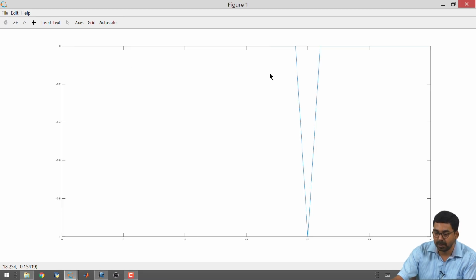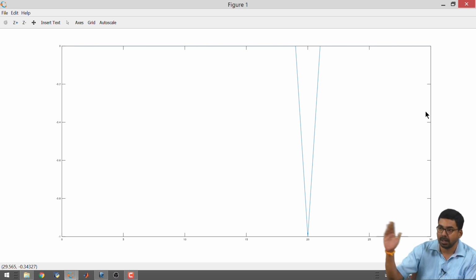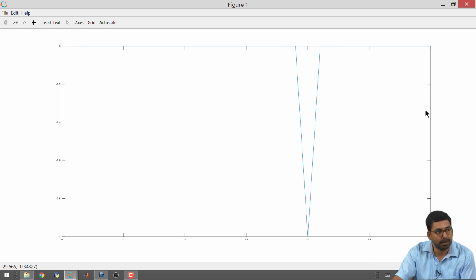The first thing that we noticed is it went to the right, flipped, and then it came to the left. That means that there was a reflection, otherwise an impedance mismatch, and this impedance mismatch, yesterday we saw that we are talking about the characteristic impedance of the medium. So, on the right side it hit a wall and it then bounced back with a change in the sign. Okay. So, the electric field flipped.